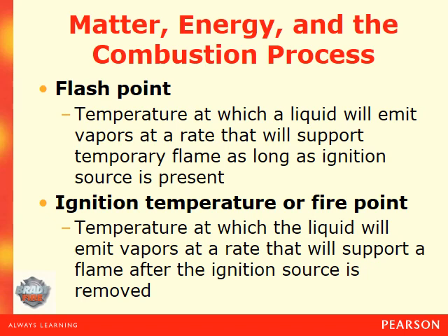However, you begin to heat that diesel fuel up and eventually it will begin to burn. And then you can take away that ignition source, that torch or say matches or whatever the case may be, and it will continue to burn because it has got to that ignition temperature or fire point, because now the fire is producing enough heat to change that liquid into a gas. And that all depends on, of course, what the product is. I'm hoping that makes sense.